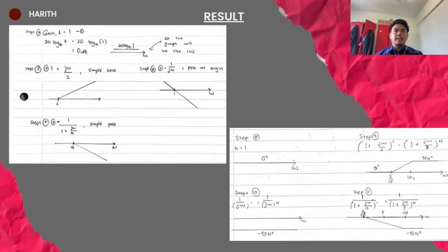When analyzing a system, we begin by identifying all relevant factors from its transfer function. The constant gain establishes our baseline, while the poles and zeros shape the frequency response. To construct a complete Bode plot, first plot each factor's magnitude contribution individually, starting with the constant gain. Zeros increase the slope, and poles decrease it. The corner frequency marks where this slope change occurs.